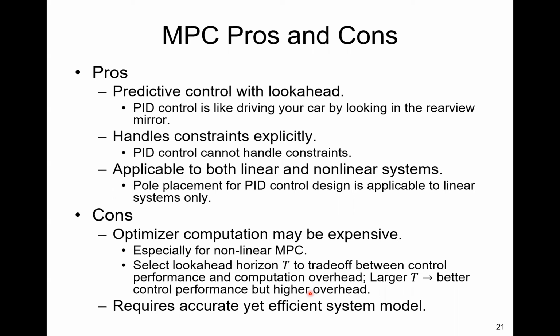MPC is so-called predictive control with a look-ahead. You're looking ahead over a time horizon and performing control based on your information in the future time window of length T. Compare this to PID control. Some people have said that PID control is like driving your car by looking in the rear-view mirror, because you are not looking ahead.